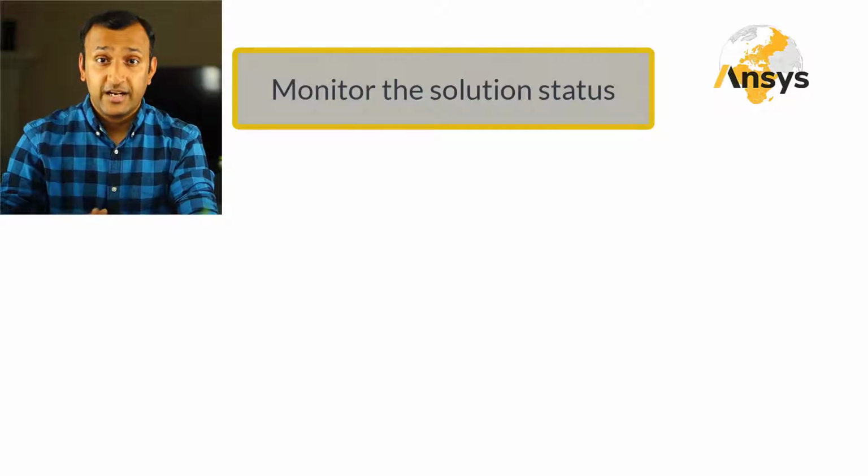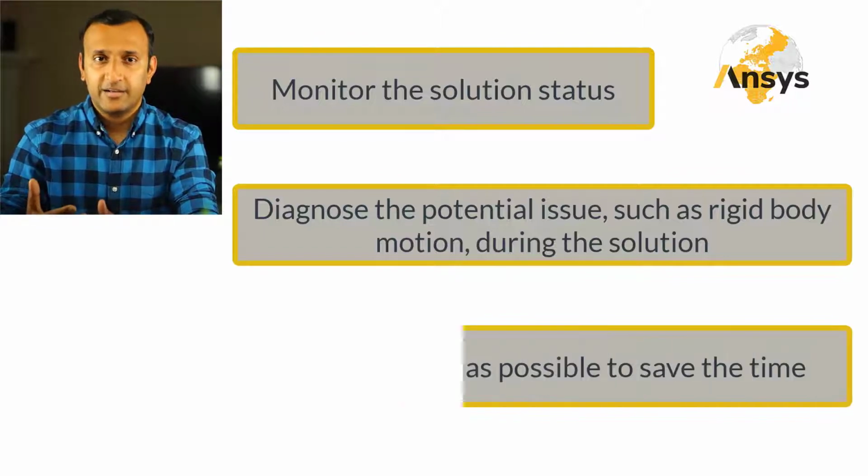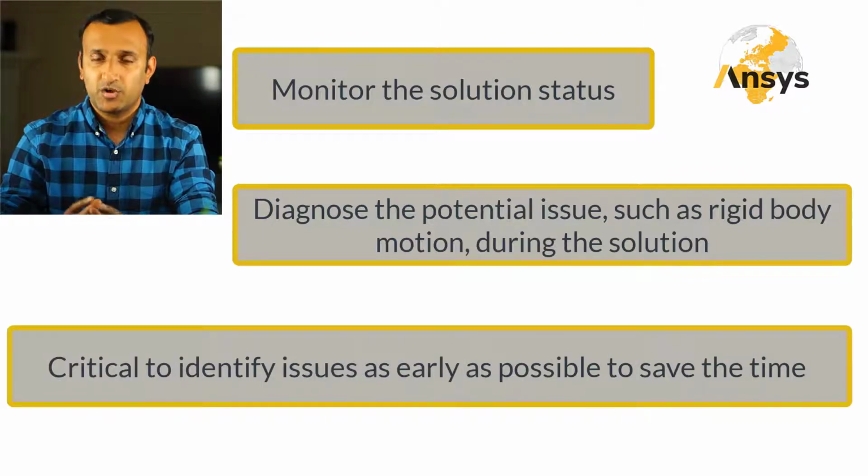Some nonlinear structural models can be time-consuming and challenging to solve. Therefore, monitoring their status and understanding how to diagnose potential issues such as rigid body motion during the solution is critical in identifying issues as early as possible. Doing this can save us a lot of time.